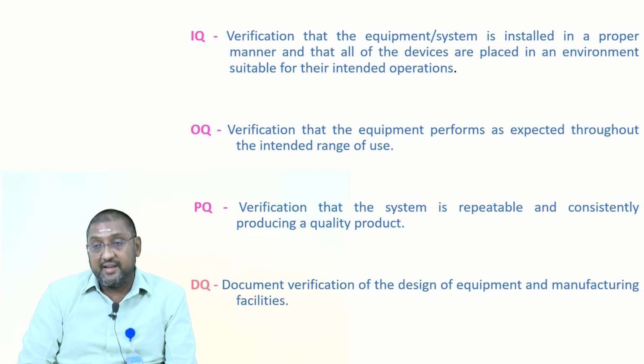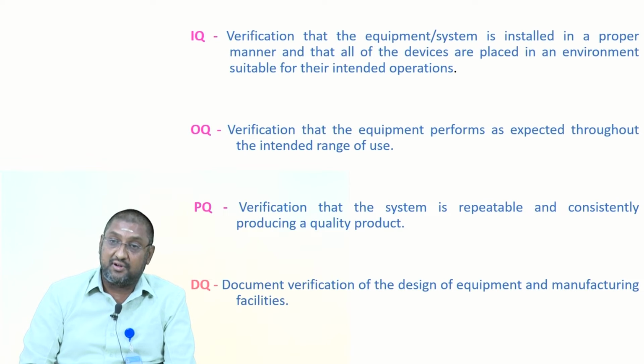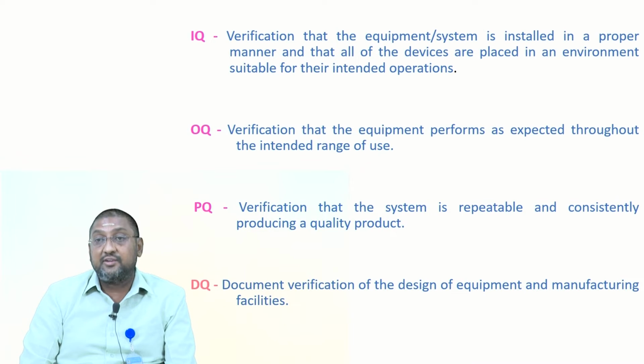The same thing applies to HPLC also. While purchasing, the detector capacity may be to detect 0.1 ppm, but after 1 year, you have to ensure whether it will still detect 0.1 ppm or not. How to ensure that? You slowly reduce the concentration of your sample and ensure whether it is able to detect 0.1 ppm or not. If it is not able to detect it, and only up to 0.5 ppm is detected, you have to change the SOP: this instrument, from this date, is capable of detecting only 0.5 ppm.